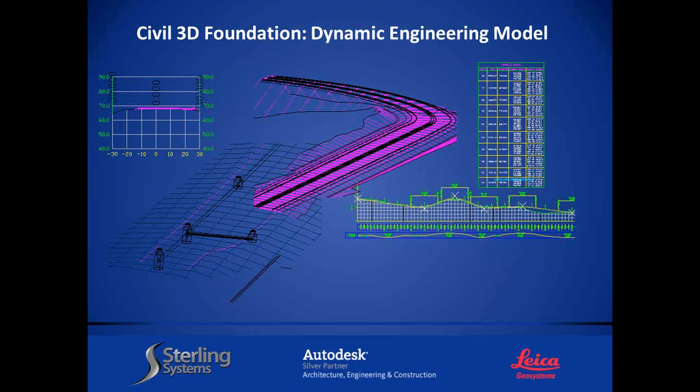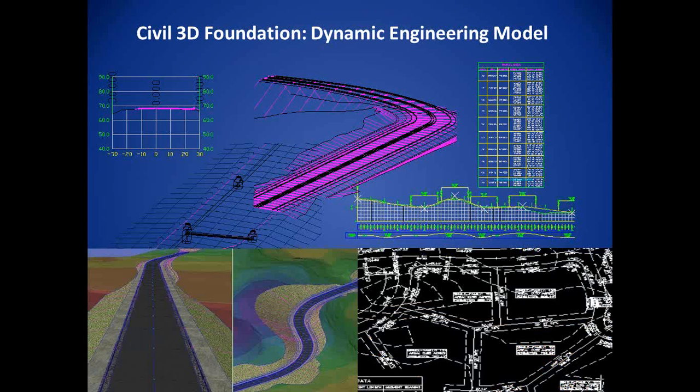So whatever's on my plan that I see on my screen, I'm going to see when it gets printed. If you think about how many hours we have spent going back and forth on that in the past. All of the cross sections, the data, everything's going to be automatically linked as well. And even the utilities, and remind me when we go over storm sewer, if I don't get there or don't show you, it is in 3D, and if you flip it up in 3D, it looks fine in 2D. When you flip it in 3D, you'll actually see, like you see in this picture, the manholes, the catch basins right underneath the surface, and you'll actually see any type of collision or clash detection. You can see where they interfere at that point.